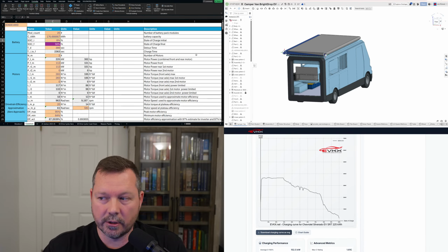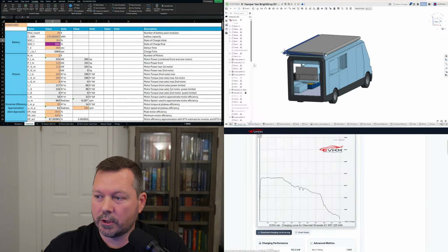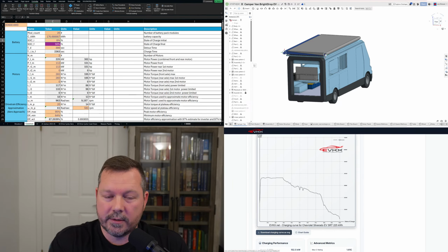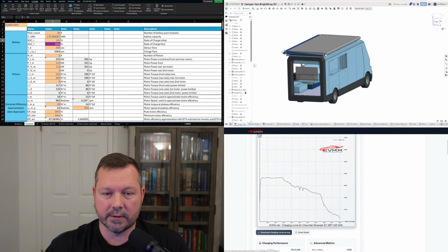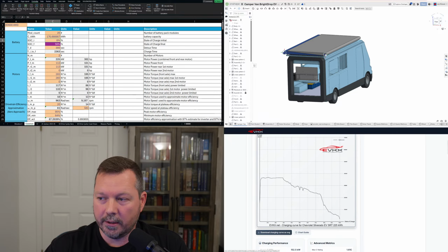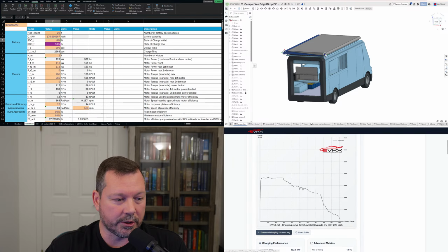And then the initial state of charge. Almost all EVs charge really fast at first. But at a really low state of charge, say 0 to 5%, they can be kind of slow. I know in the Tesla in particular, if you get into a charging station and you're less than 6%, it predicts that you're going to get there low, so it stops preconditioning the battery, so the battery's not warmed up and ready to go. Then when you plug in, it's got a slow charge, and it's using that to warm up the battery, and you don't get up to speed until 10% or greater. So it's actually faster if you get in right around 6%, plug in, and then you've eliminated this real low state of charge area.